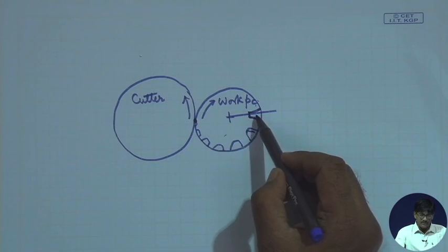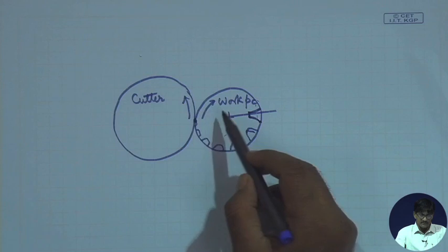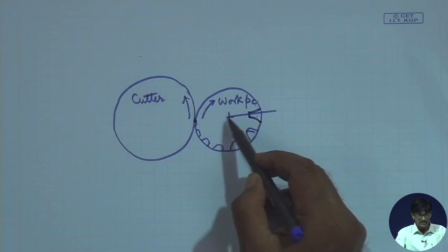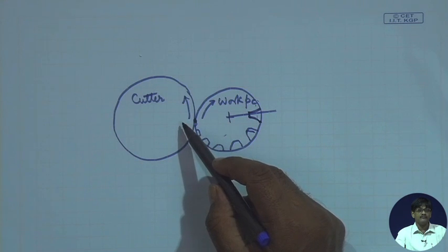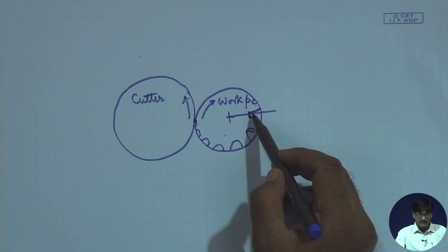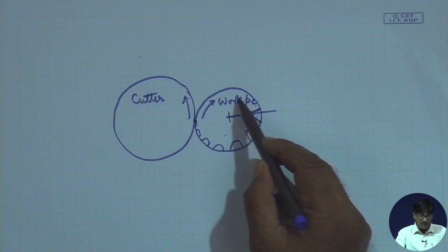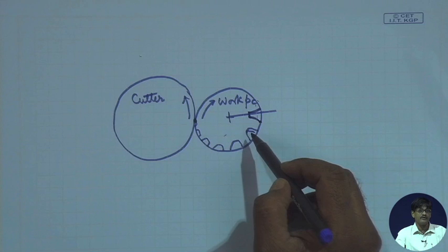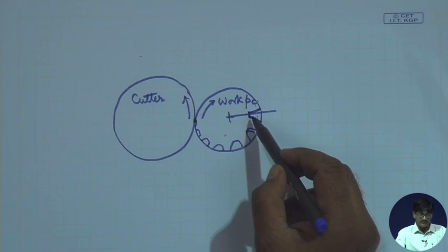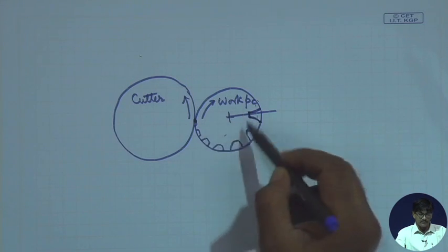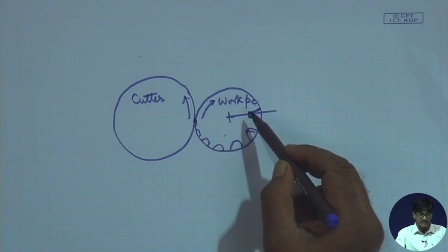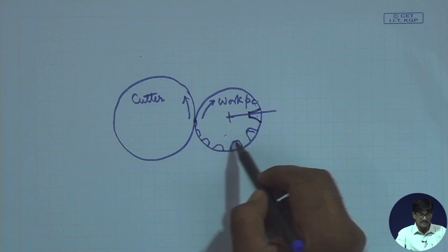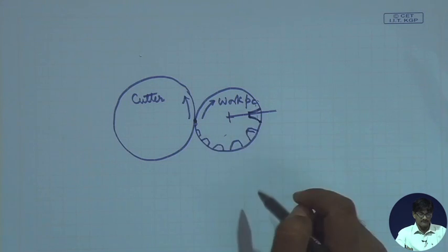At that time, there will be a dwell. That means, they will go on rotating still, while this one does not undergo any infeed. At that position, we have to ensure that all of the teeth undergo this particular full depth, and therefore at least more than one rotation is made, so that the cut is taken up by all the teeth on the periphery.